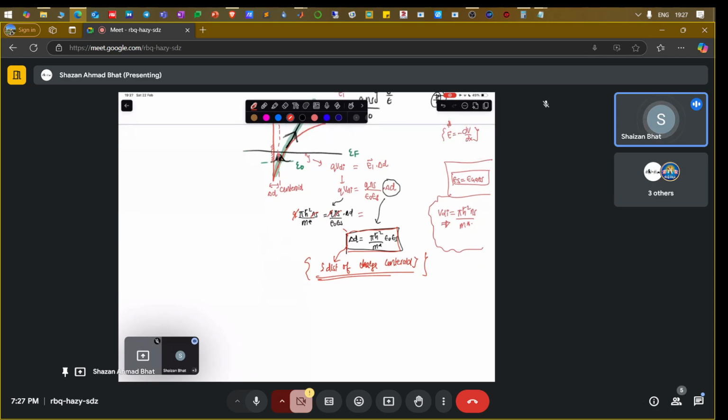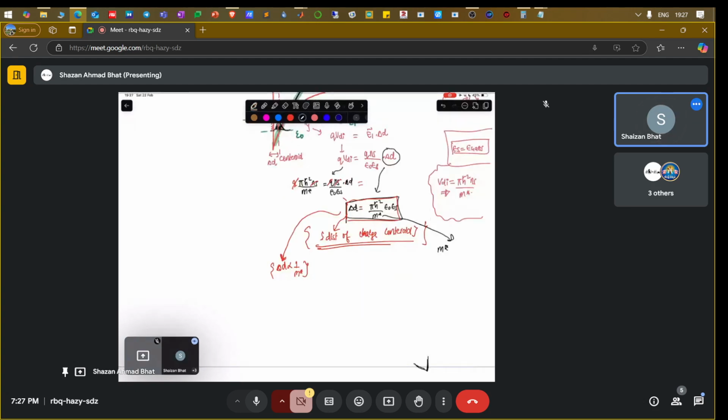And you see that this particular distance is inversely proportional to the effective mass of the electron. How it is intuitively inversely proportional to effective mass is a different question, because effective mass is the sum total of all the quantum mechanical effects summing up into a certain parameter. You know that effective mass is equivalent to h bar square over d square E over dk square, which comes basically from solving the Kronig-Penney model and other things.